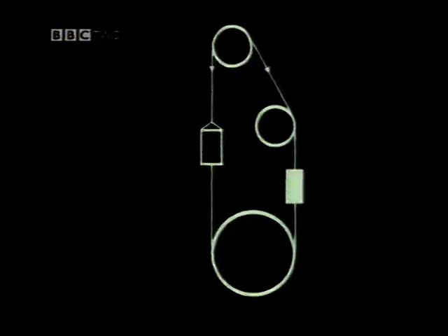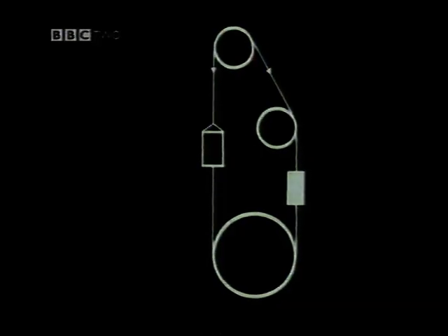So we've established the total system load, including the rope weights. What's the next step? Well, we know the amount of traction that we require to move the system, and we have to make sure that we have sufficient traction between the rope and the sheave to drive the whole system. Please remember that we're relying upon friction between the sheave and the rope to effect the drive. So, how do we relate friction and traction?